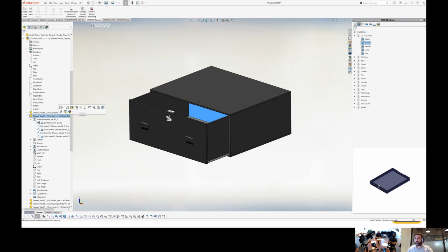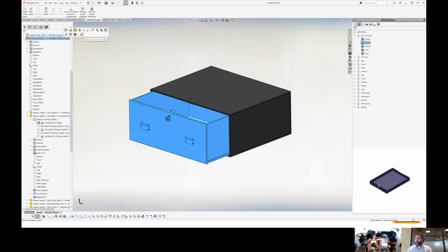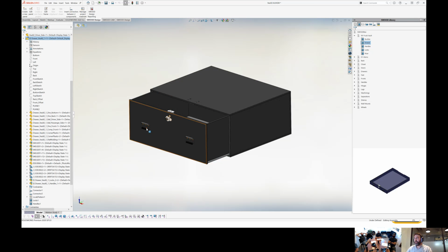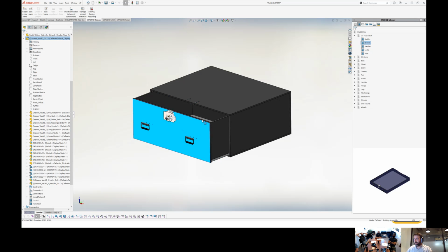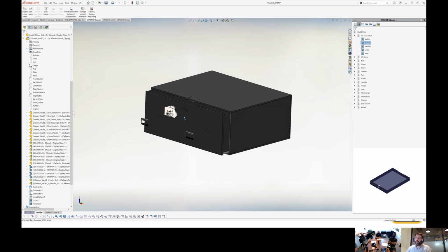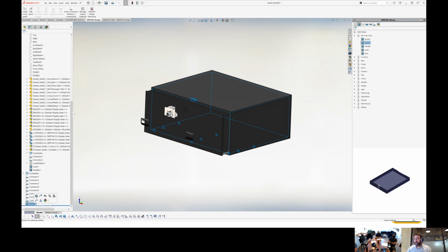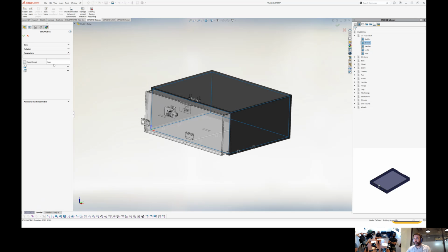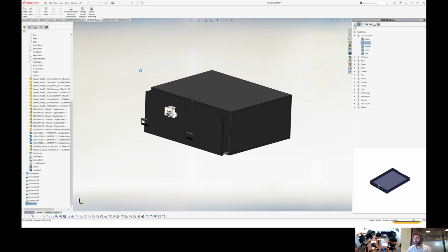That's it. I could use the flexible options, but the only thing is, as I have SWOOD boxes for the handles and everything like that, these are not following directly. I need to open the drawer and everything to do that. If I manage that with a SWOOD parameter, it's going to do that for me directly. And we can add as many as we want. Yeah, after you can totally manage that in another way, and that will be good at the end.